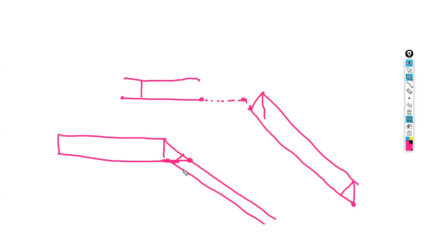So whether you're using topsoil removal or topsoil replacement or not, you can actually put in a 0 offset for this, and it will calculate where the subgrade slope ties to the embankment slope, for example. And again, a really easy way to create new surfaces from existing string data that you may have.